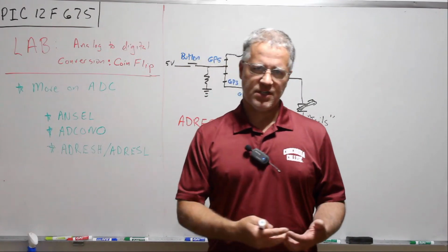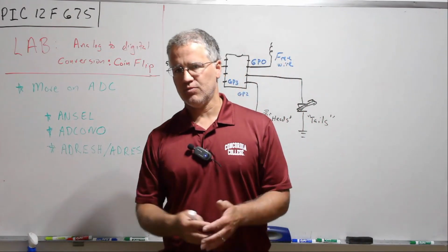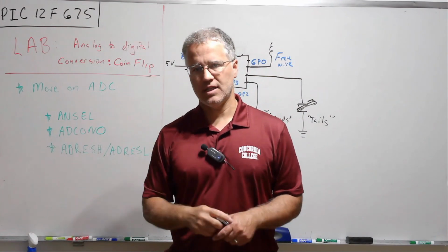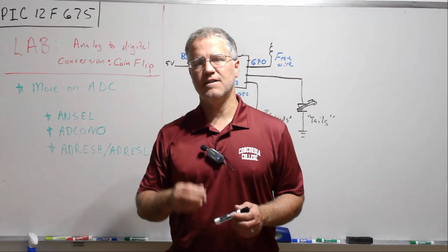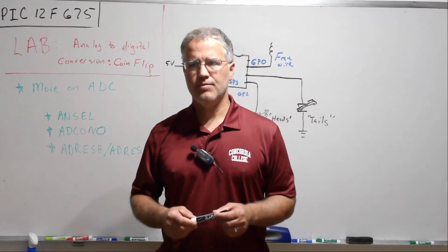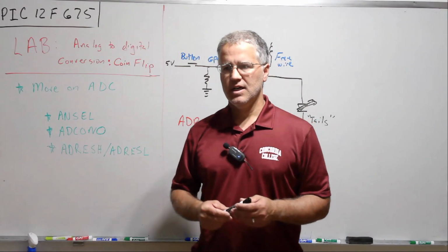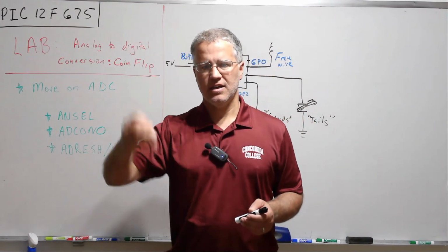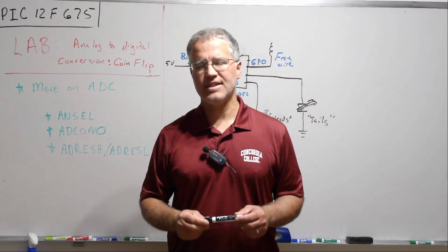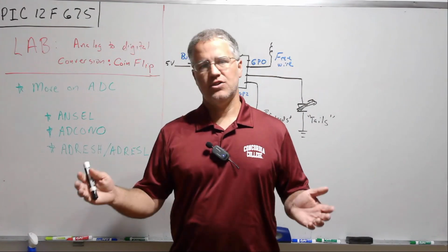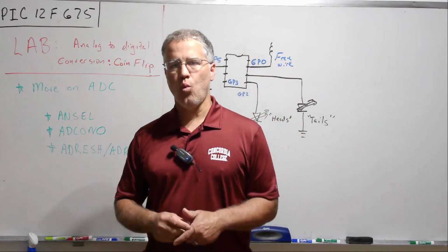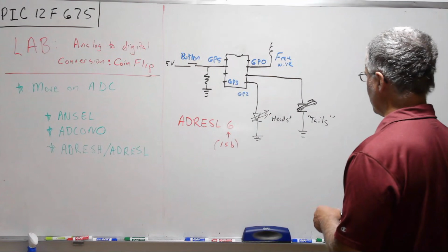We aren't going to do some statistical checks on that. Maybe if you want to take this project further, you could actually record the output and see if it behaves in a truly random way. But I think to a good approximation, if it's just grabbing a noise signal, the least significant bit should be a random distribution, 50-50 chance of a 1 or a 0.